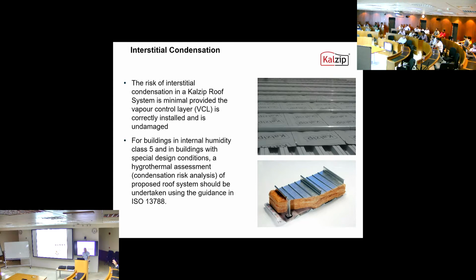All these studies that you were mentioning one by one will define what type of VCL you need to use, because condensation is what usually kills the system. If you have a system with condensation inside, that will destroy it. So all these studies, one by one, type of building, class of building, all combined will let us tell you what type of VCL to use to avoid that vapour crossing the dew point.